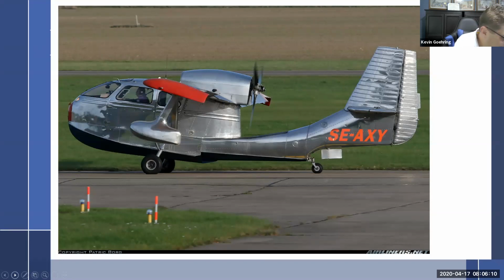But anyway, all right. So this would be a pusher. Now, any engine can be used as a pusher, but you guys have built the Lycoming and you know what the thrust bearing is. If you make it a pusher, it's the slinger ring on the crankshaft. And so then you have to think about, ooh, maybe that wasn't the best idea. But it's what it is. The slinger ring becomes the thrust face. So, this is the pusher type.